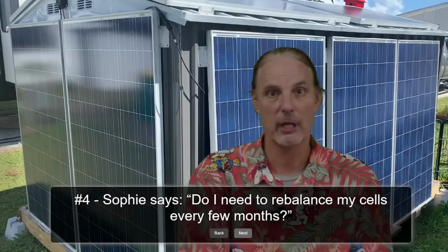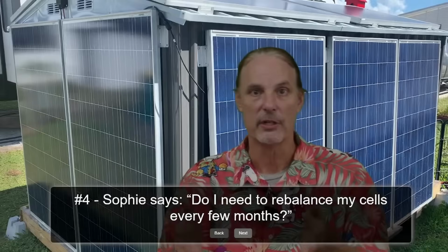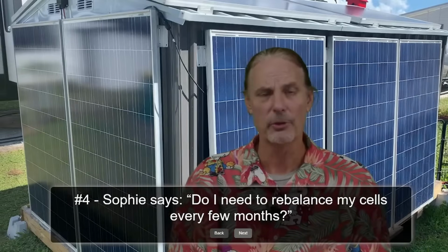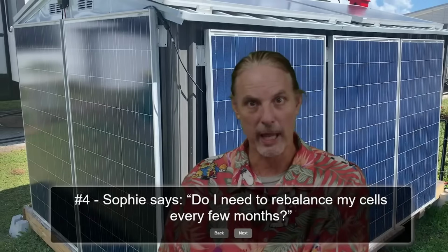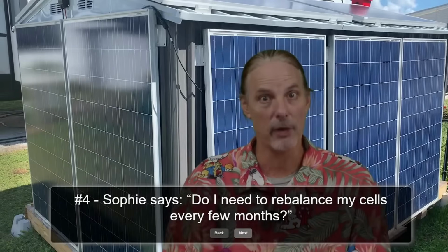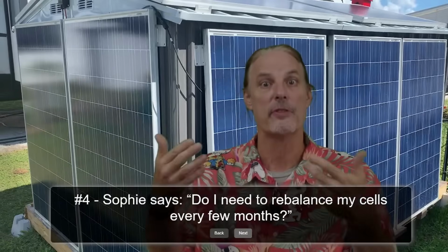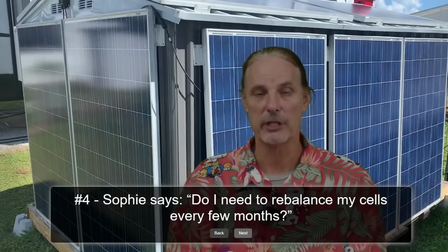You can say, if I get over 56.2 volts, and I have less than 1 amp going into the batteries, then that means that the batteries are fully saturated and they're of a sufficient voltage that they no longer are charging, then I call it 100%.